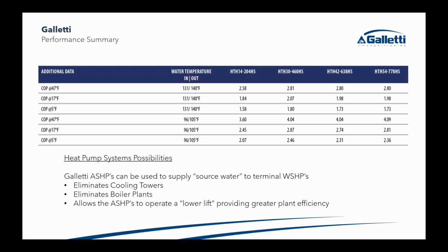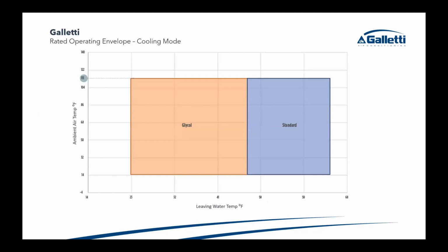Yeah, okay, good. This is just showing the standard water temperatures, as mentioned before, that AHRI 550/590 that they developed for chiller systems. There's been some tailoring to it, obviously, with this we're improving our heating. But if you look at our cooling charts here, there would be better. A lot of the details are pulled from 550/590, but there is no standard at this time. That's why you have everybody saying that they're in compliance with 550/590. This is just showing the operating range for the outlet water temperature for the cooling mode, produced down at 23 degrees. Obviously, you must have a glycol system at that point.